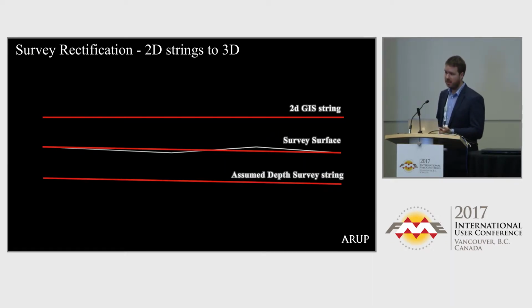And then we had an assumed depth. Very similar to the assumed size, because of the nature of light rail, we got a nice track slab, so we raised up all our assumed depths so that we would get a hit if it had an assumed depth. Anything that had absolutely any values assumed on it would be classification D, with classification A being that you've touched the pipe, it's there, you know how old it is.